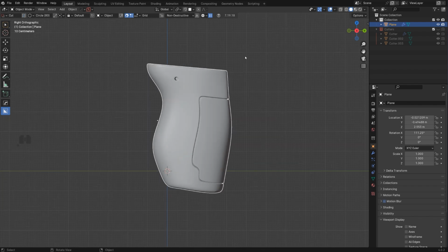And sometimes you need to simply use retopology because the mesh is so complicated and has so many details that it would just be a headache to solve the puzzle of quads on it. So it's easier to run a retopology, it's just faster. Also, you can use tools like the Retopoflow add-on, which is going to make it super easy, okay?